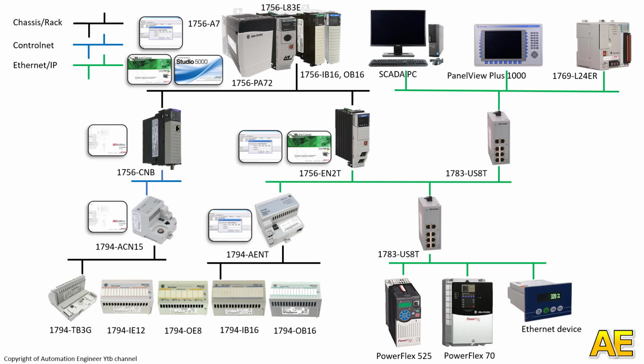For Ethernet switch Stratix configuration, we use the web browser. And for configuration to monitor and change the parameters of the VSD, we use Drive Executive, or we can change them directly in Studio 5000. But for me, I like Drive Executive more.